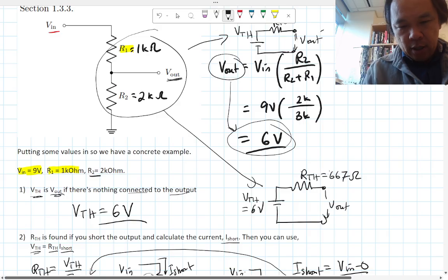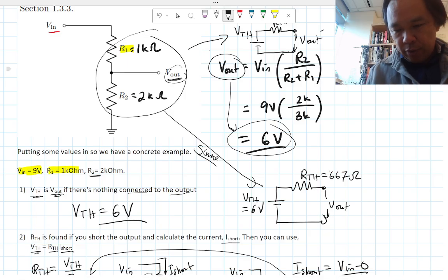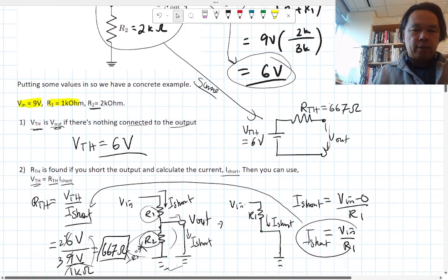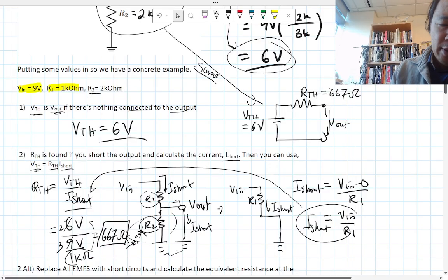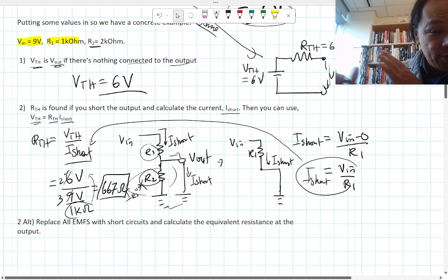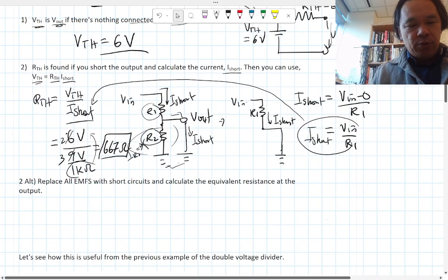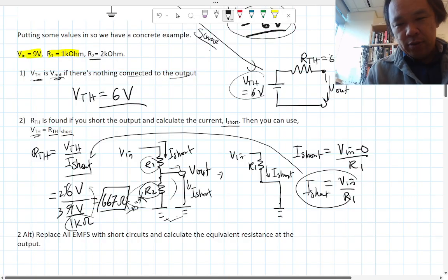These are the same. They will behave exactly the same if the output is here instead. So you basically reduce the number of components from 2 resistors to 1 resistor. Of course, you can do this with a more complicated circuit, and reduce everything from like 1,000 components down to 2, basically 1 voltage source and 1 resistor.